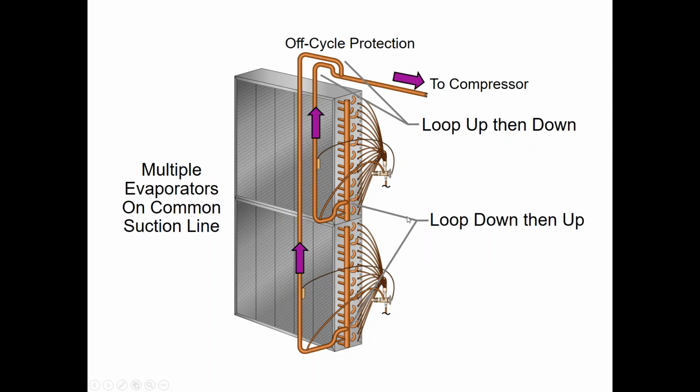In piping these coils on the suction side, one of the first things we want to think about when we manifold together is, are we properly draining that coil? So we always want to think about the oil that's in the evaporator coil. The oil's being carried from the compressor through the liquid pipe to the TXV. We get into the coil, and depending on what our load is, depending on what our capacity is, maybe we have a 3 compressor circuit and only 1 compressor is running, now our capacity is reduced, our refrigerant velocity is reduced, and the oil starts dissipating out.